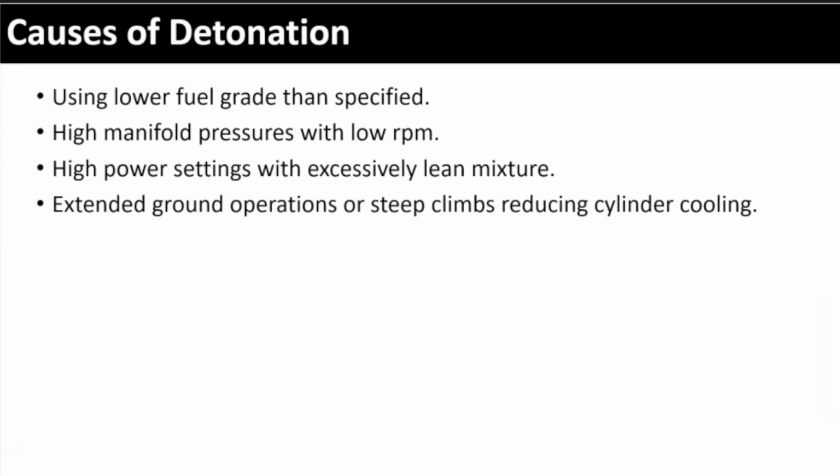This is another one. I don't necessarily worry about the extended ground operations. We don't sit on the ground too long around here. Steep climbs, right? If you're in a steep climb, what kind of power setting do you have when you're taking off? Full power, high power. It's going to be burning hot, right? As you're in a climb, there's more and more heat being added to the engine because you don't have what to cool it off.